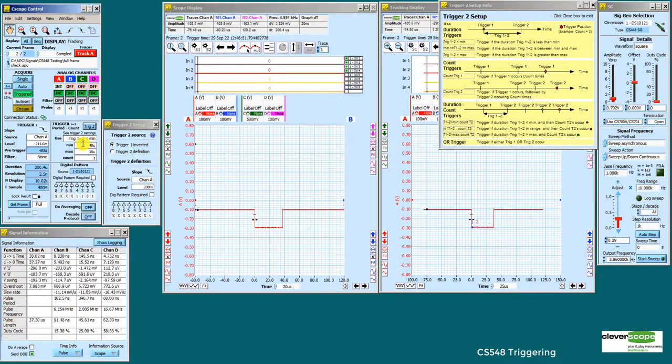Now if I increase the time, it stops triggering, and if you look over here at the pulse length, we can see that as we come down it triggers, and as we go up and I'll very slowly go past the 40, it stops triggering. There it triggered at 40 microseconds. So anything less than min and we will trigger, and we're doing this over a single pulse.